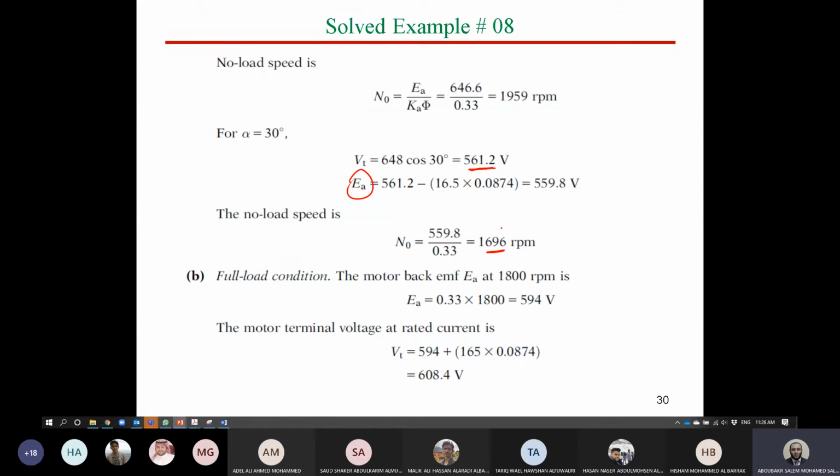Right. Is there any question? Is it clear now? How we can control the motor speed by means of controlling firing angle? Yes. So we can say now at firing angle equals 0, we can get the maximum possible speed. This is the highest value of speed control range. And at lower value of firing angle, at lower value of voltage, we can obtain the lower value of speed. But what will be the value? It depends on the operation of your converter.